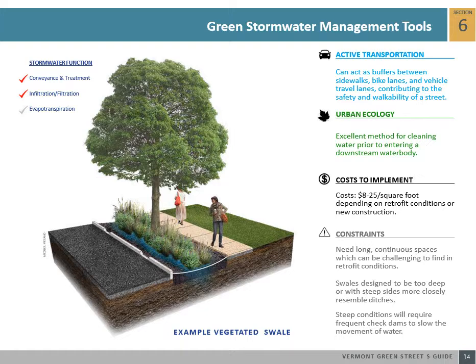While infiltration of stormwater is a possibility, the primary purpose of using green gutters is to filter out pollutants and slow the flow of water using only a narrow strip of landscaping. Like a swale, but possible in highly space-constrained areas where the sloping sides of a swale are not feasible. Green gutters introduce green space along streets that lack landscaping, provide a landscape buffer between vehicular traffic and pedestrians, and create desirable and safe street conditions for people.